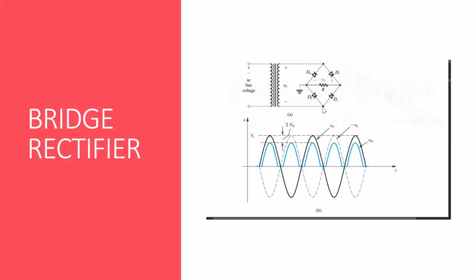As the bottommost point has negative potential, D2 is forward biased and D3 is reverse biased. So through the journey, we can see that there are two diodes in the path. So 2 VD will be the voltage drop here. And again, this is a nice way to use the full wave of the sinusoidal input curves.